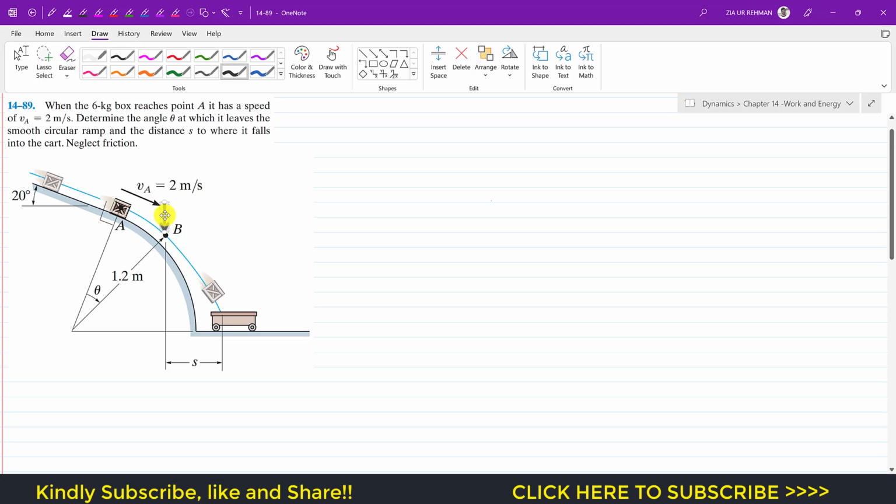And if we consider the normal and tangential coordinates, the normal axis will always act towards the center of this circular ramp. So this will be our normal axis, and the tangential axis is going to act in the tangential direction, right? So in the direction of the tangent to the path. So this is our tangential direction, like this. So this is our positive t.